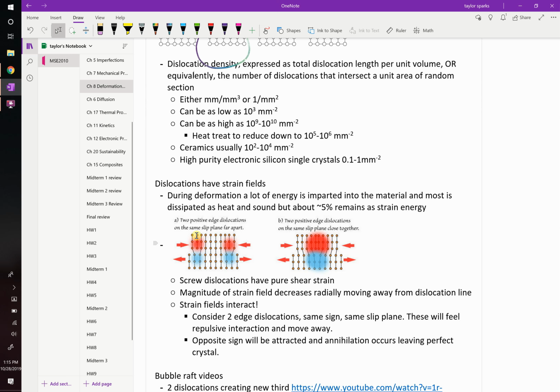If anybody has done CNC milling, some materials like Inconel, you can't really CNC Inconel very easily because it work hardens so much that each time you pass over it with the little blade to cut a section out, the layer underneath it gets harder and harder and harder.